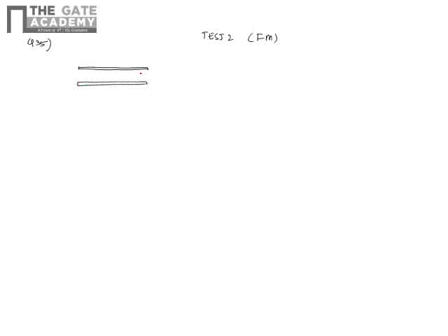In the front view, the top view is given in the question. So basically the objective is to measure viscosity. The bottom plate will be fixed. On the top plate you will apply a force F, which is required to keep the top plate moving at a constant speed of 5 meters per second.